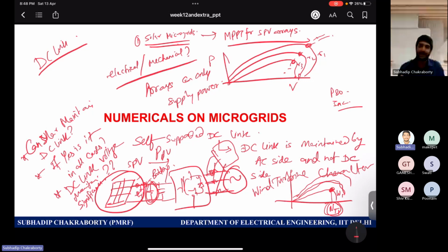with the stator terminals to allow the regulation of the voltage and frequency, and also enable the MPPT operation by controlling the current. Controlling current means controlling the torque of the machine. You can actually change the speed. Some kind of field-oriented control you must have heard of, and you can make the total system operate in the desired speed range, such that the MPPT operation, due to the mechanical characteristics of the turbine, is enabled for that given wind speed. You want to trap the maximum power from the turbine and then push it through the generator into the grid. That is the complete essence.